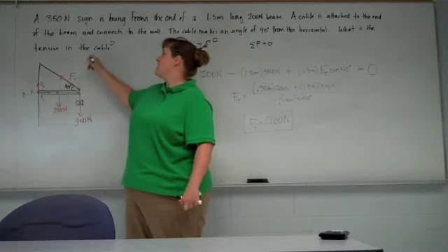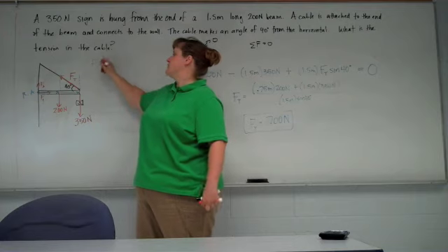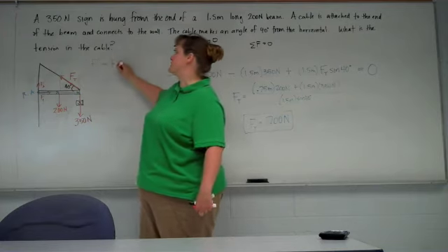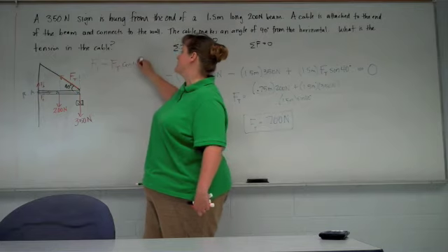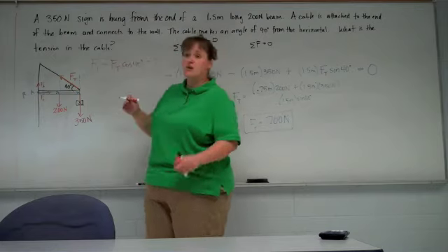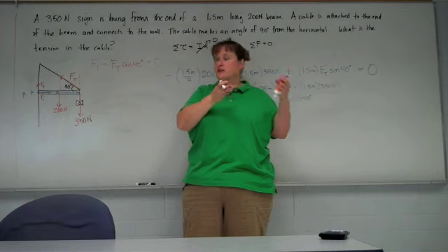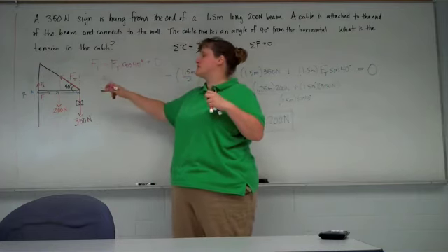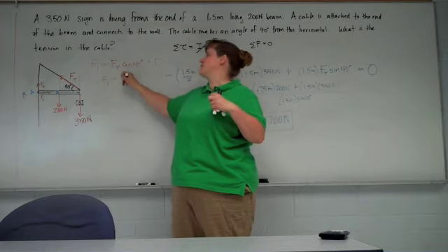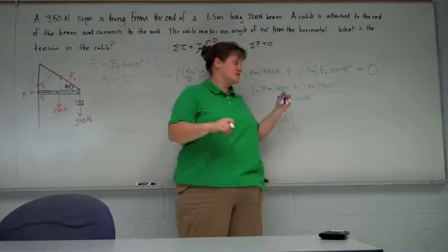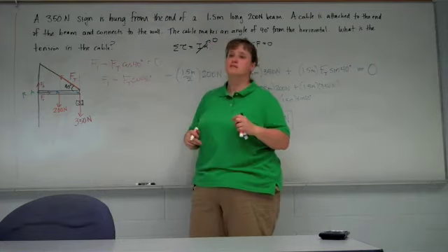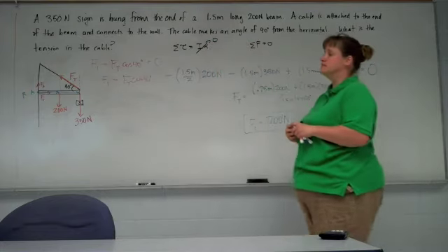So we'd have F1 to the right minus the horizontal component of tension, so force of tension cosine 40. That would have to equal 0 because it's not accelerating along the x direction. So F1, that horizontal force that the wall is exerting on the beam, is simply the force of tension, 700 newtons, times the cosine of 40 degrees. That will give us F1.